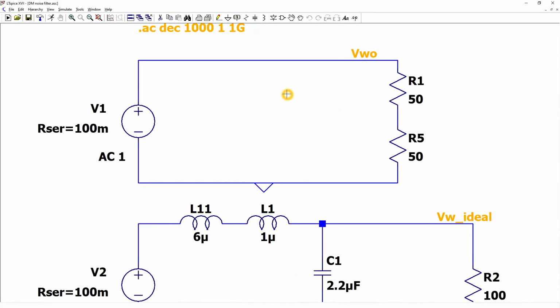For the differential mode in the conducted emission test setup, the noise current will flow from our source through the plus high potential wire, through both resistors in LISN, one from the termination and the second from the spectrum analyzer, to our minus return reference wire to the source.